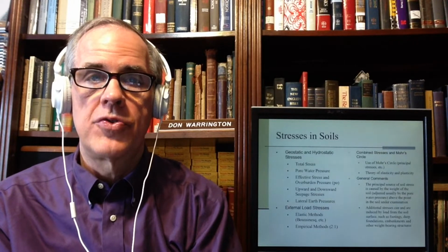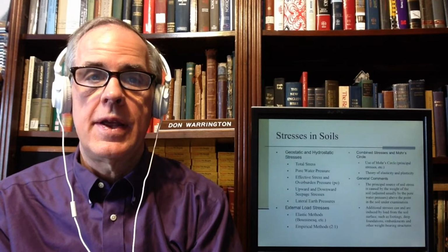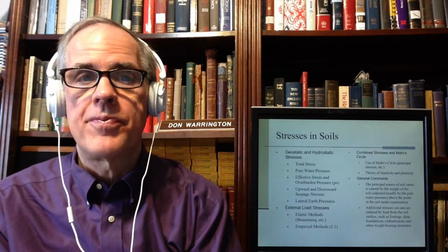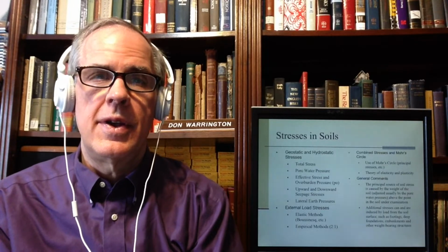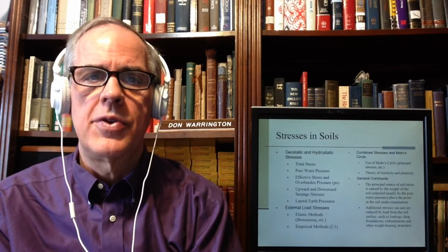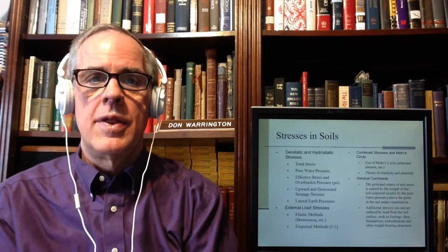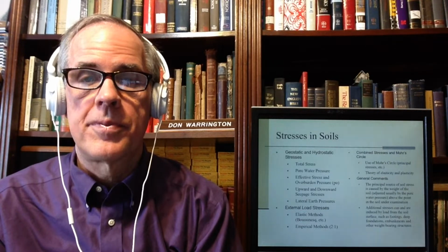In soils, we can't do that, because soils, by their own weight and by the effect of gravity, are stressed when we start, and then we come in there and add stress to it. And occasionally we'll take away, but usually we add stress to it, and the understanding of what's there to start with is essential.